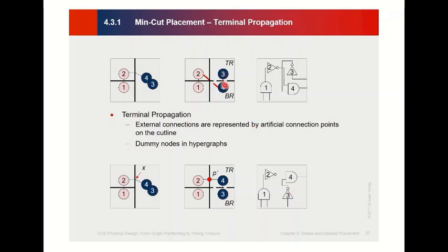If we put 3 and 4 the other way, you can see that in the end we have quite substantial wire in order to finish our connection. So very long wire here instead of very short wire, and similarly output here go to the input, very long wire, instead of output go to the input, very short distance. So there is an algorithm called terminal propagation to solve the proper placement, but I'm not going to go through this exact algorithm.